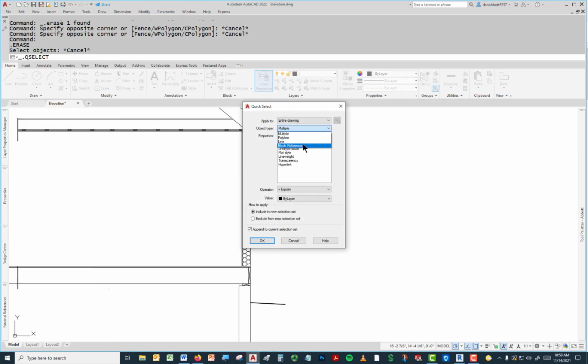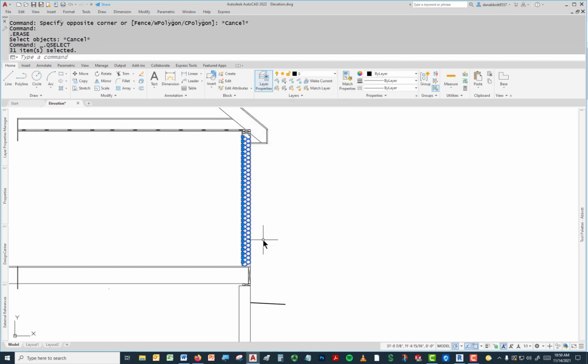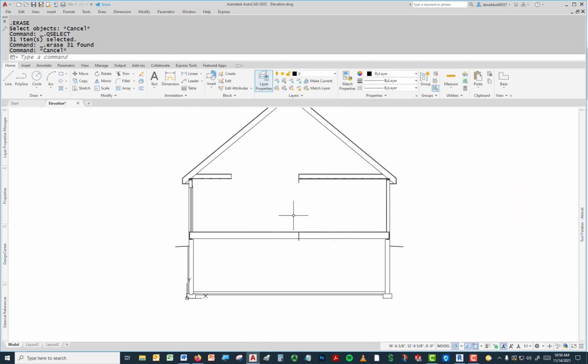And in this case, what I want to do is get all the block references whose name equals, and I'm going to come down here. I've only got 2 block references. That's the one I know I made the name of that odd, so that it wouldn't be anything that could be duplicated by anybody else. Now when I press the delete key, those are gone, and I don't have to worry about selecting anything.